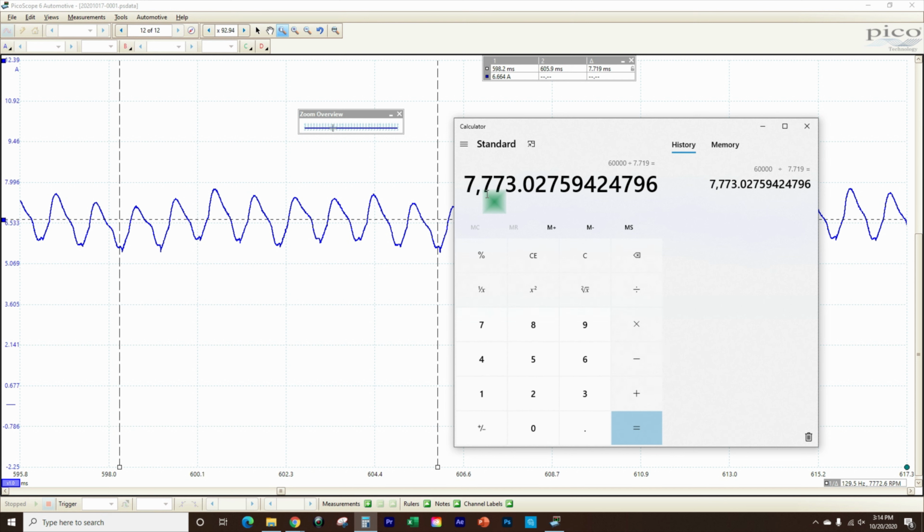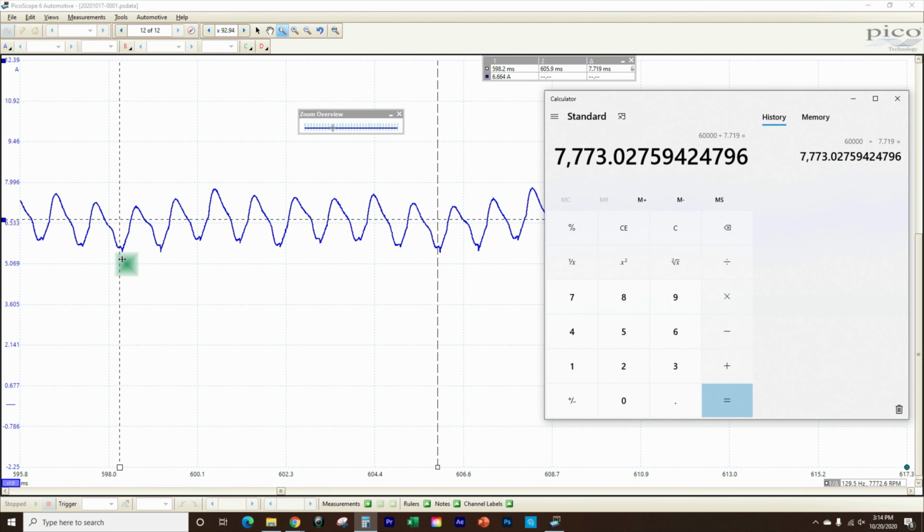Now, I said that around 6,000-ish was pretty normal. You know, I'm not going to get too excited that this thing's spinning 7,700. The vehicle wasn't being driven right now. It was under low demand. The amperage is normal. And I wasn't really going for a problem. So this isn't really all that strange. I'm pretty happy with 7,700 RPM.